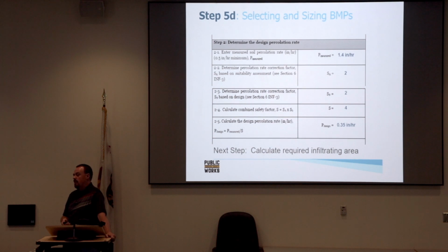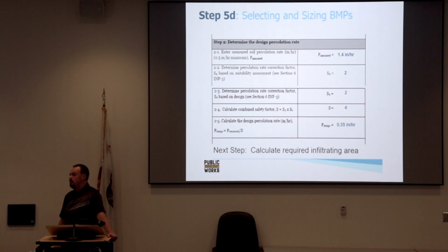And in that area, we're actually averaging at 5-foot depths over 200 inches per hour. So the ground is actually infiltrating faster than the pervious concrete. So the bottleneck is the BMP itself, which is kind of weird. But in that case, we had over 60 feet down to groundwater. So we felt fine. If it was maybe 5 to 10 feet, we may not have even developed that project.